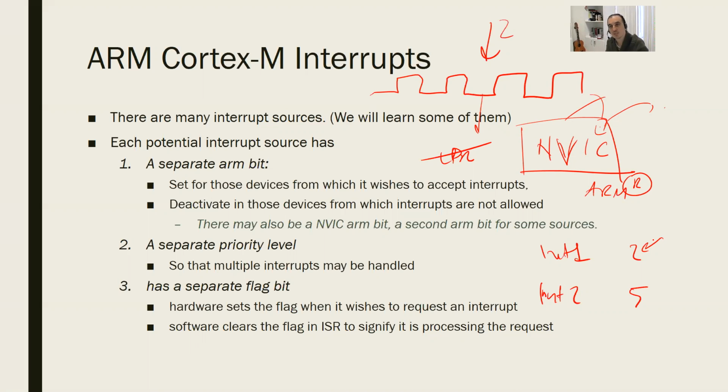Just like the prioritization in networking, we have a prioritization for interrupts in the microprocessor. How will we set it? Again, there will be a control register to set that priority. And actually, I haven't told you yet, but there will be a global priority level at the microprocessor. We will say, let's only accept interrupts above some threshold level.